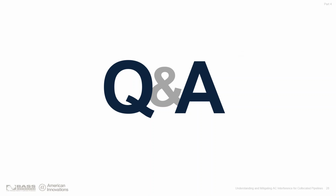Perfect. All right. First question, what about the transposition of HV lines? I think the timing of the question came in just before you addressed the transposition. So yes, when the electrical lines roll and they rotate, that is an area of concern where you'd want to see a change in your EMF, and then that would induce a difference in your voltage potential on your pipeline. And of course, when you have different voltage potentials, what happens? Current starts flowing. So right there where you see a roll in the electrical line, that's definitely where you'd want to put in a remote monitoring unit.